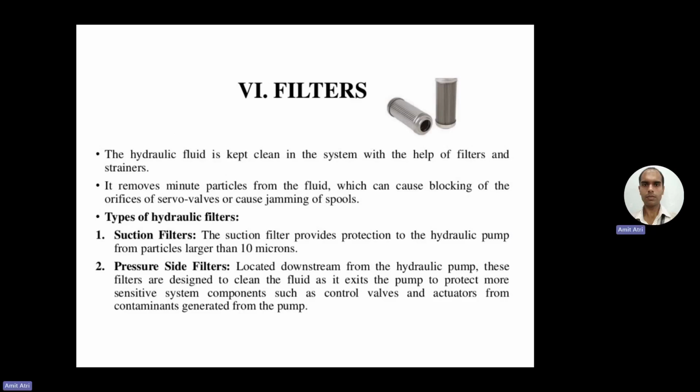Next is filters. So the hydraulic fluid is kept clean in the system with the help of filters and strainers. So it removes minute particles from the fluid which can cause blocking of the orifice of the servo valves or cause jamming of spools. Then types of hydraulic filters.